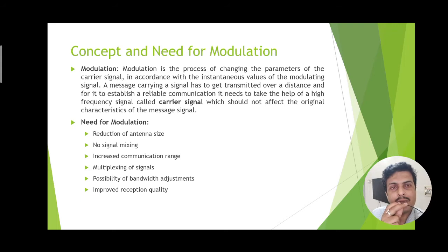That means whatever is the low frequency, low power message signal, it needs some carrier which will carry this low frequency, low power message signal to a long distance, and afterward that carrier will be removed so that the message could be extracted for the receiver purpose. So the process of converting this message signal, that means riding this message signal over the carrier signal, is known as the modulation process. Similarly, at the receiving end, when the message is extracted from the modulated signal, it is known as the demodulation process.